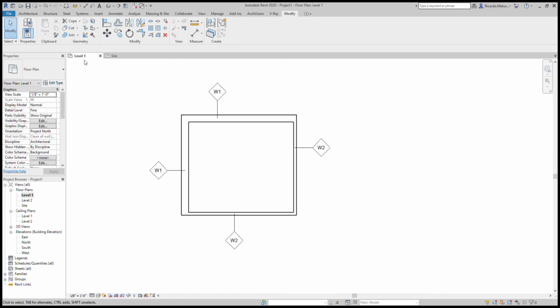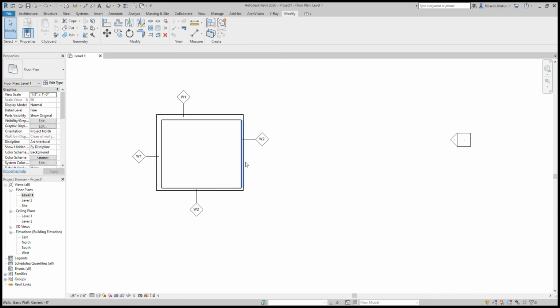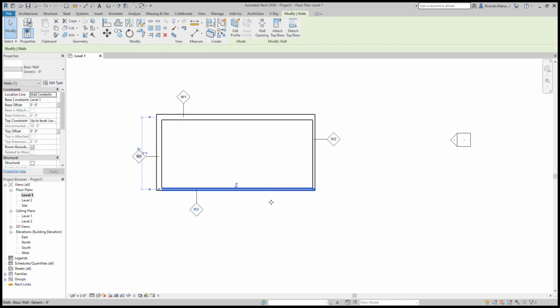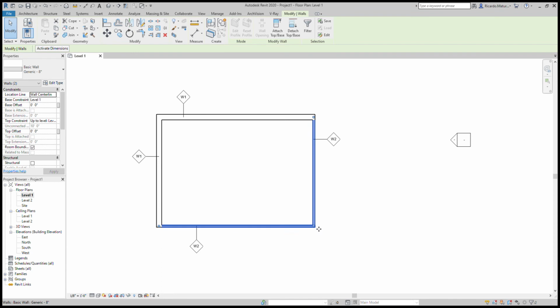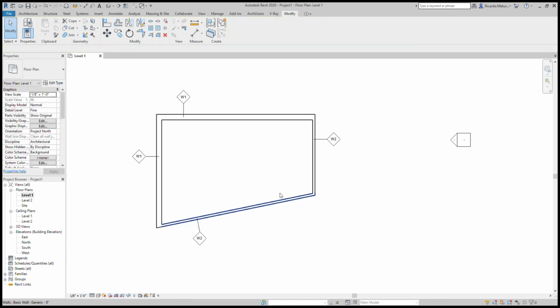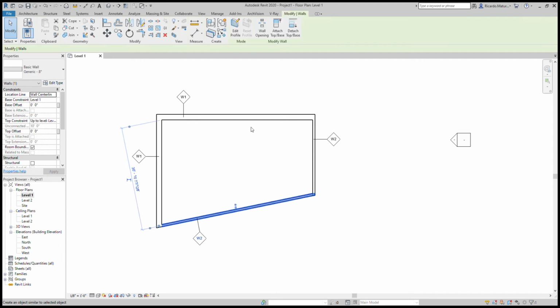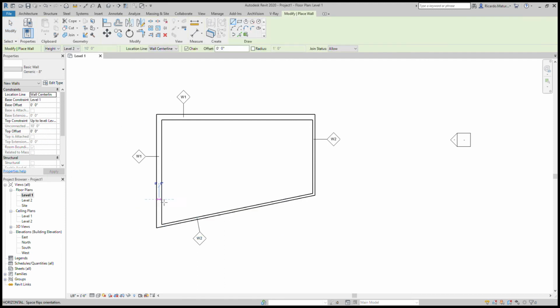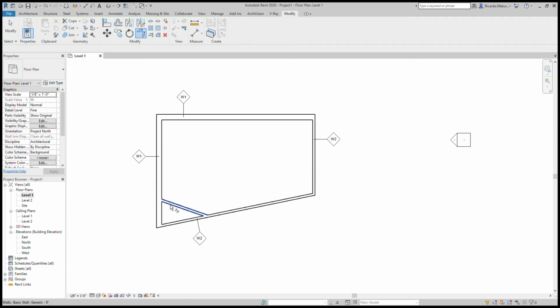So now let's go back to our ground floor. Now you can start pulling. You can grab them both, and there's a dot, and then you can change the angles. You can do all kinds of things. You can add new walls. You right click and then you create similar. And then if you press TR, or trim, that's a trim tool. You can trim them. You can change how they intersect, or the wall joints tool.